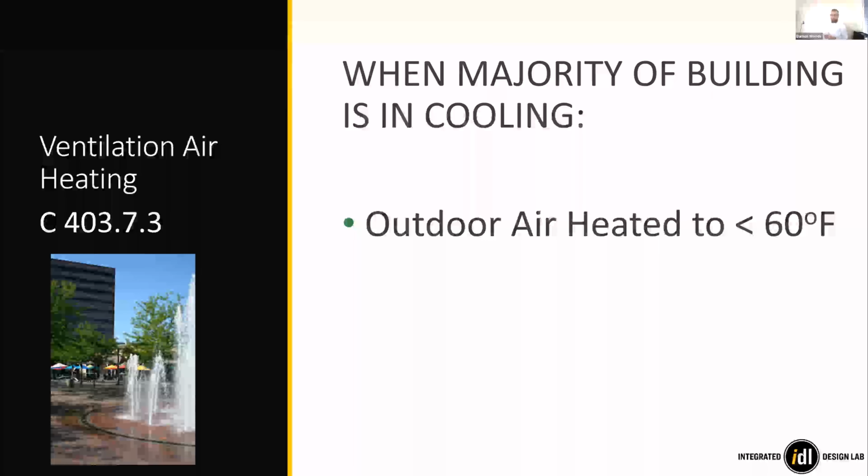You generally do want to have the outdoor air heated for ventilation, at least to a certain extent, especially in a dedicated outdoor air system, because people don't love the feeling of a 40-degree draft on their neck when they're sitting at their desk, when you're supplying that. So if you have your heating and cooling separate from your ventilation air, that's why they try to maintain closer to like a 60-degree temperature.